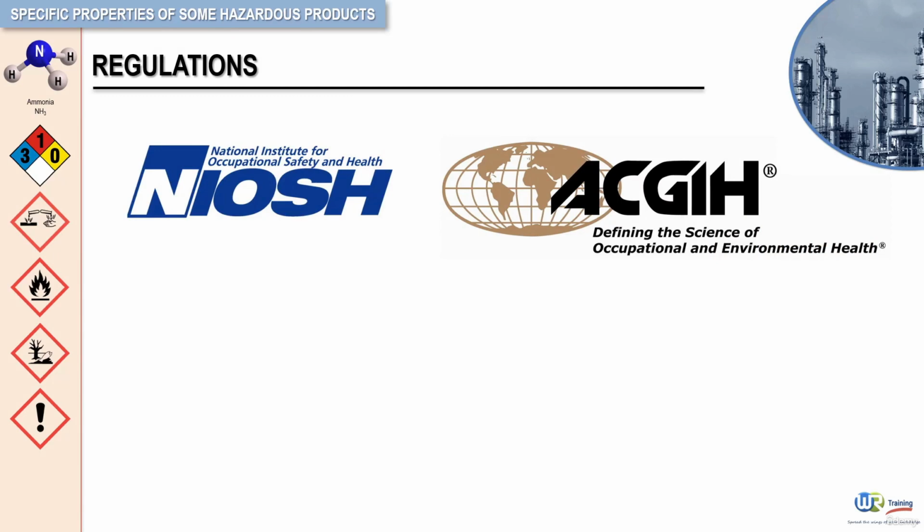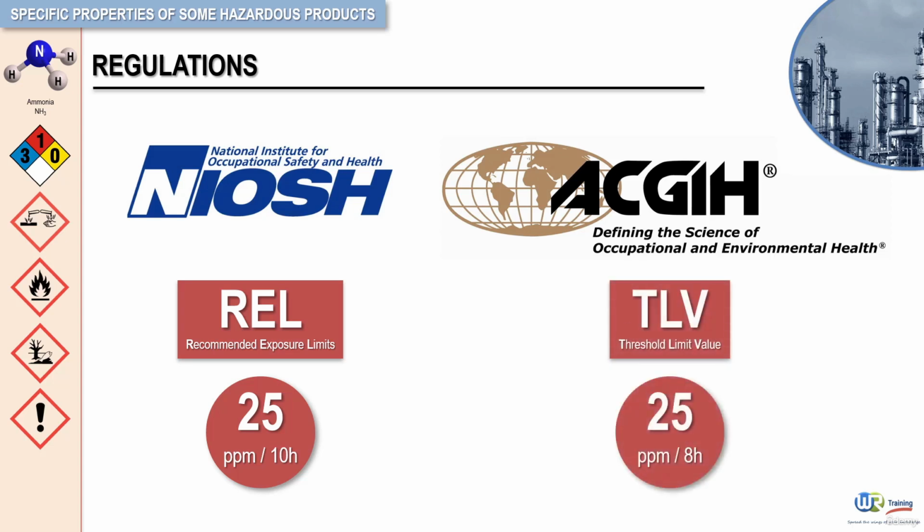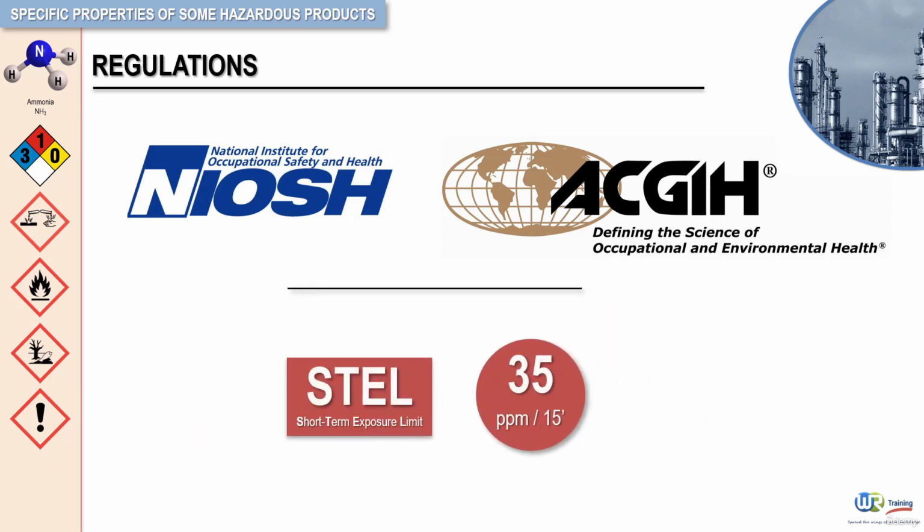The first one publishes a recommended exposure limit, or REL, of 25 parts per million averaged over a 10-hour period, while the second one published a threshold limit value, or TLV, of 25 parts per million averaged over an 8-hour period. These organizations also recommend a short-term exposure limit, or STEL, of 35 parts per million for a 15-minute period of exposure. Now, it is important to note here that the recommendations of these two organizations are not legally binding and often exceed OSHA's requirements.